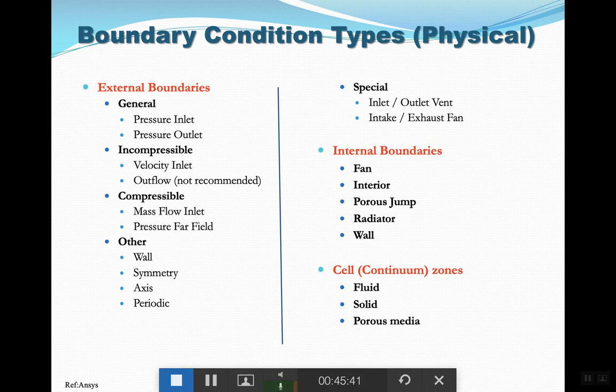So the way ANSYS solves a control volume for unknowns is that it assumes everything is a boundary condition. That might seem strange, but that's the best and most optimized way of going through the numerical simulation for ANSYS. So what it does is you provide your conventional boundary conditions, whatever it is, to the cells.